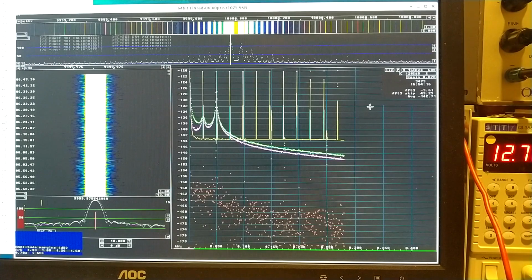So I would have to reset, but this thing is linear all the way down to 0 offset, I can assume. So it means that it doesn't affect the readings I get down to something like minus 135 or so. And that happens at 2 Hertz offset. So I can trust numbers up to 2 Hertz offset from this measurement.